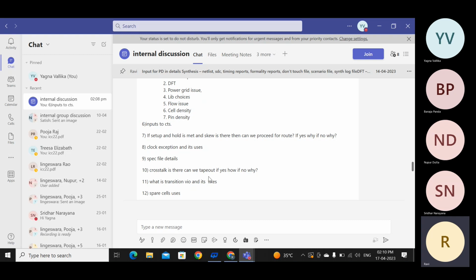If adding insertion delay and transition time, your transition time should be between 8 to 12.5% around that. If you see too many buffers getting added, you can relax it slightly, but don't relax the transition requirement below 20% of your clock period, or like 100 picoseconds around that, so that if your clocks are sharp, then you will have a good database. Add aspects like fan out. So no issue with that.